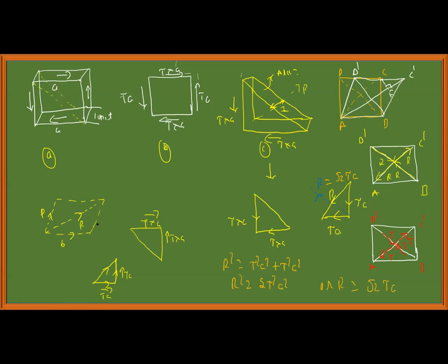If I take the reaction forces, the diagonal is the resultant. This resultant will be acting from this point. Similarly, I have drawn the resultant from this point. This is under tension. For equilibrium, there should also be one force acting in the opposite direction. Similarly, if you take the other half of the body, it will be under compression.